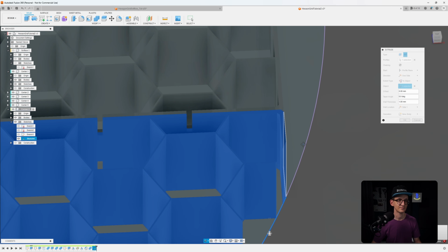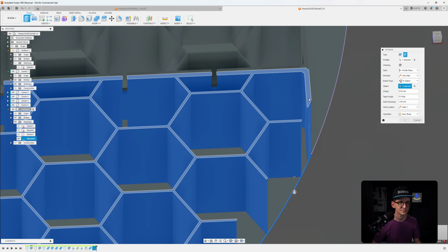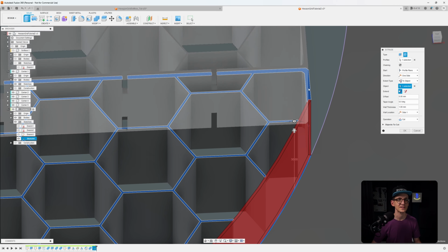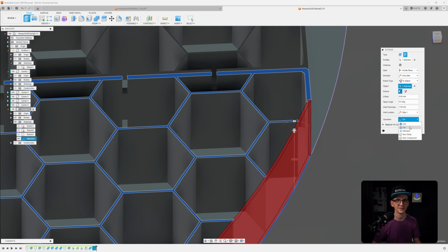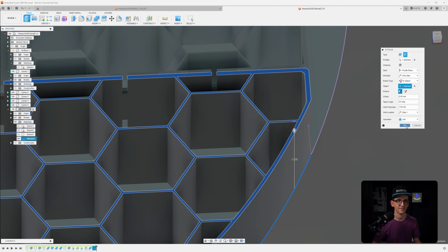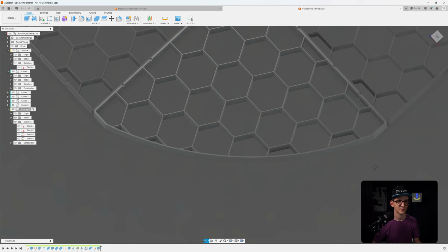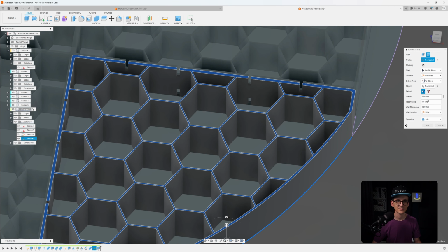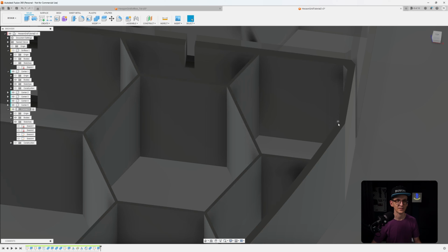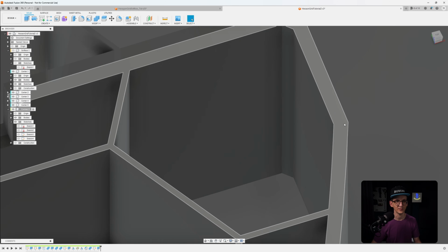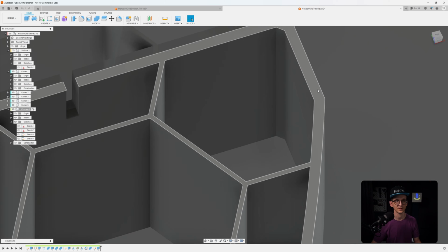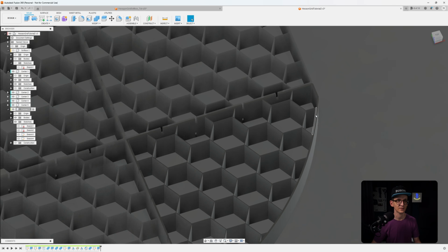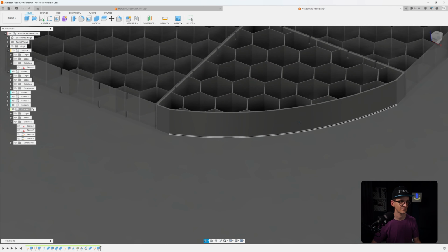I think I missed, okay, right. I missed selecting the surface there, and hit join and be good. Now we kind of repaired, and I forgot something. Go back into the thin extrude, and instead of the 1 millimeter wall thickness, we go with the outer thickness that we defined earlier, matching what has been there already from the original outside thickness, going then into the arc as we wanted. And that's exactly what we want.